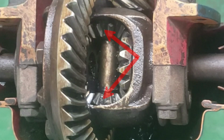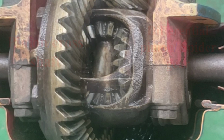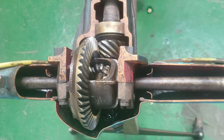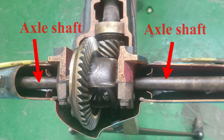There are two bevel gears called pinions that are constantly meshed with a beveled axle side gear on each axle. The pinion and axle side gears are contained in a housing called the differential case. Through the two pinion gears in the case, in mesh with the pinion gears are two side gears that are splined to the inner ends of the axles.